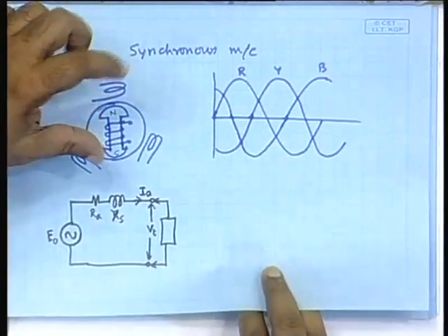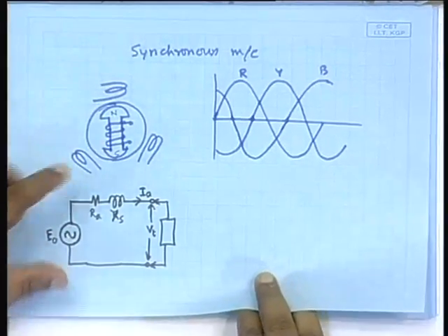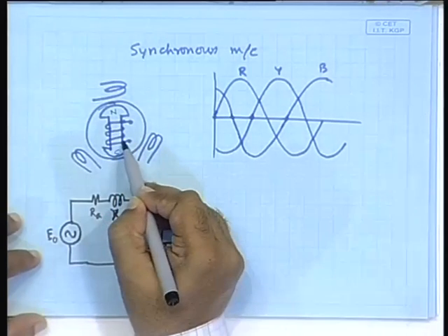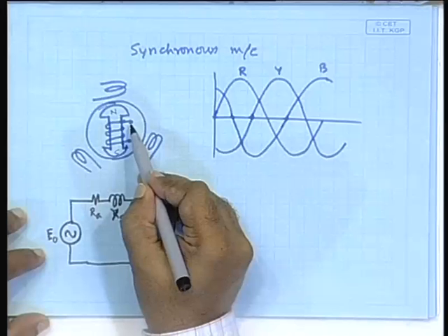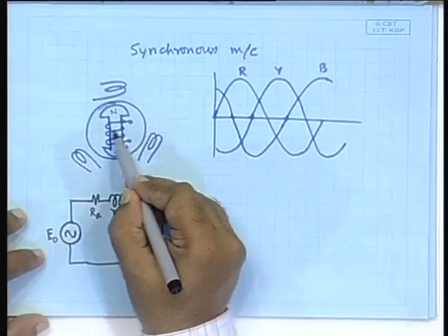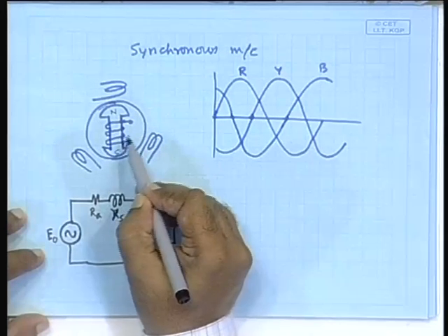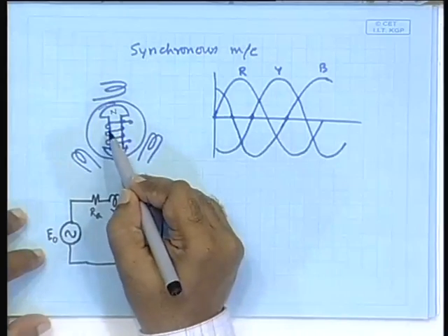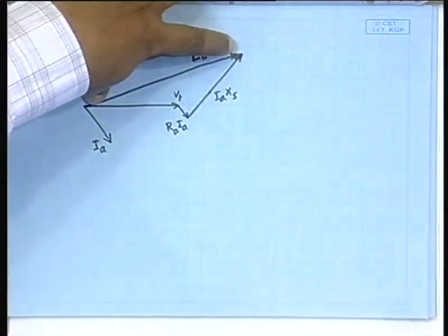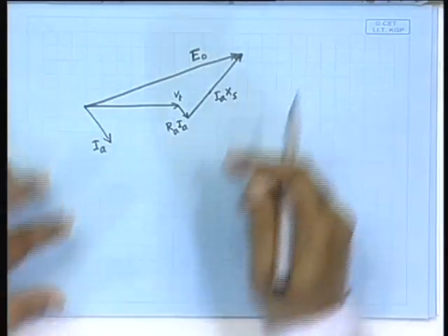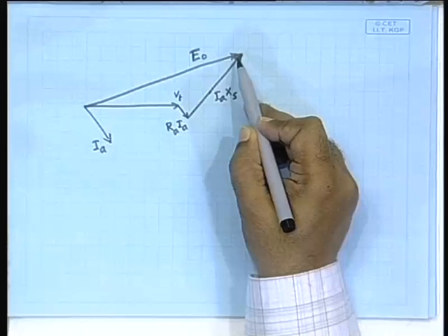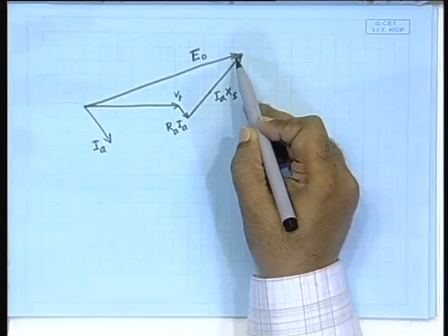So, effectively, this voltage will be dependent on the flux, and that is generated by this winding, right. The flux is being produced by the magnetizing winding, and by varying this current you can vary the flux generated. So, you can vary this quantity. Depending on the character of the load, you can always generate the required amount of generated voltage.